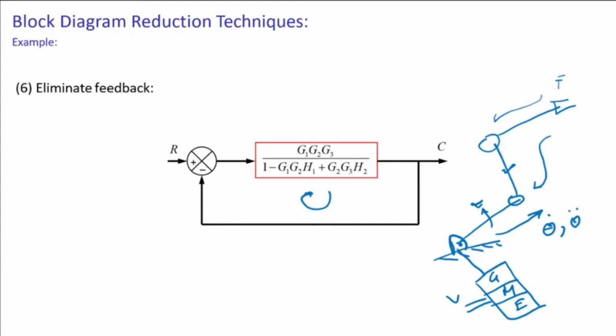Now, because of this propagation, the motion of any of the links has an effect on the forward links. This is basically what we get from our dynamic equations. We know the dynamics consist of inertia forces, Coriolis and centrifugal forces, and gravity forces. And the controller here, the independent joint control, has no way of knowing the dynamics of the system. It is just controlling the joint based on the desired position it has to go to. This is a position controller, and it doesn't know the dynamics, and there is no way of computing it. So what the dynamics does to the system is it starts disturbing it.